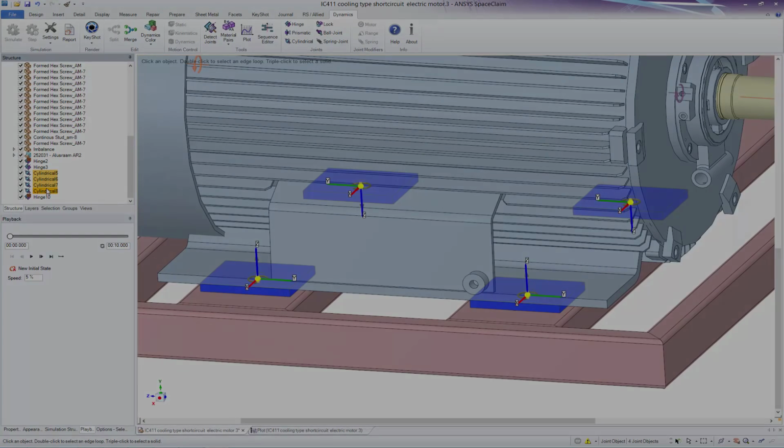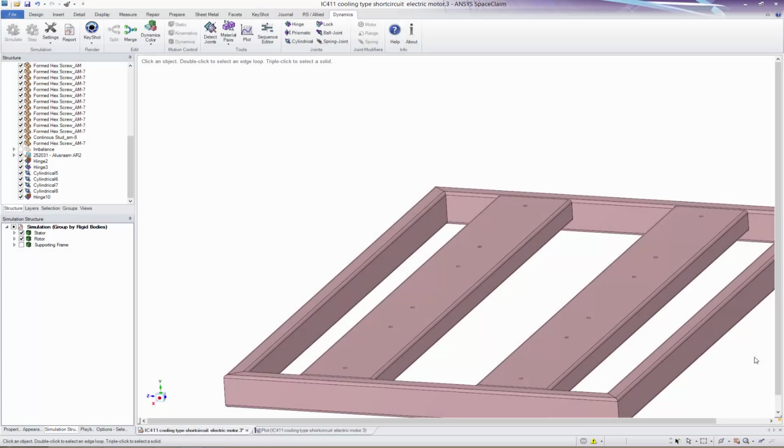If desired, one can capture the dynamic response of the supporting frame and other substructures by implementing the lumped elements method. But in this case and many others, we can assume that the frame is stiff compared to the suspension elements and thus irrelevant to the analysis.